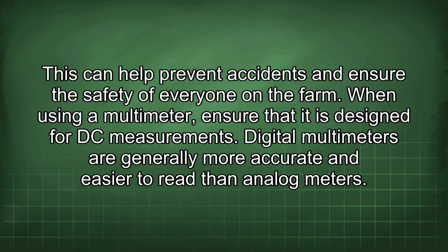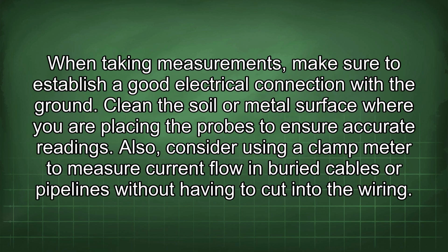When using a multimeter, ensure that it is designed for DC measurements. Digital multimeters are generally more accurate and easier to read than analog meters. When taking measurements, make sure to establish a good electrical connection with the ground. Clean the soil or metal surface where you are placing the probes to ensure accurate readings. Also, consider using a clamp meter to measure current flow in buried cables or pipelines without having to cut into